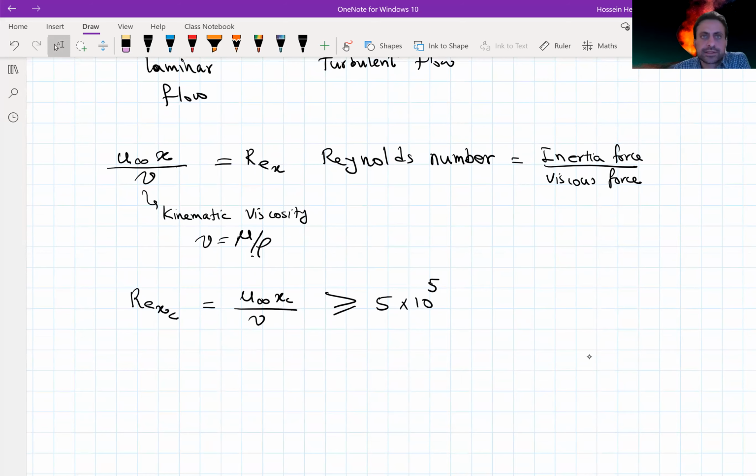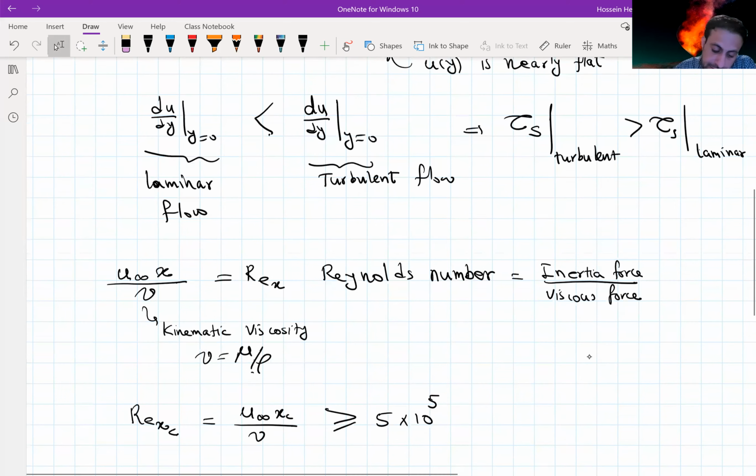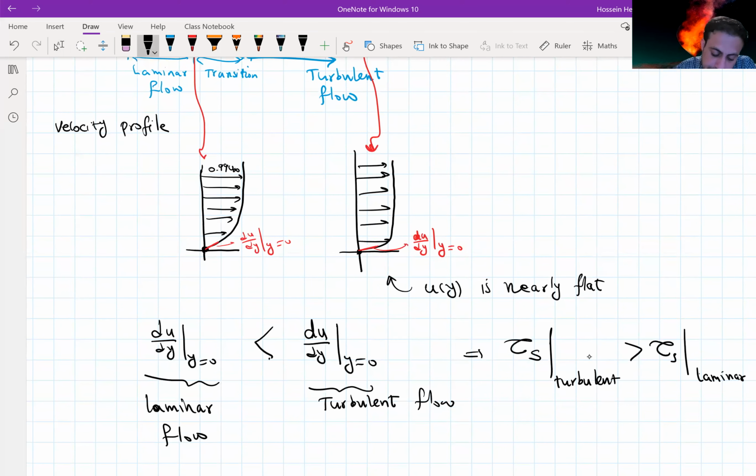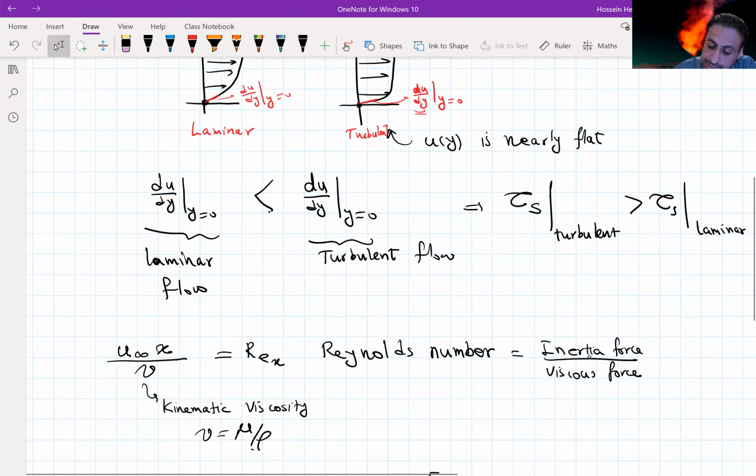That's one thing. And the relevance to heat transfer here is similar to what it can cause to the velocity profile. Let's say from this laminar flow to turbulent flow, we see there is a sharp velocity gradient that results in the increased wall shear stress in the turbulent conditions.